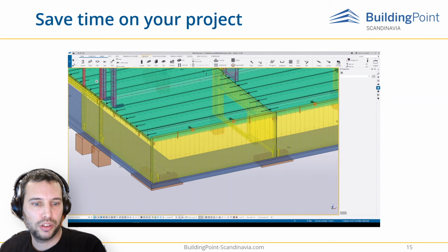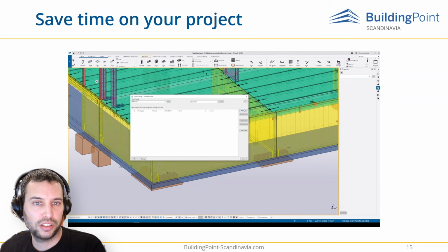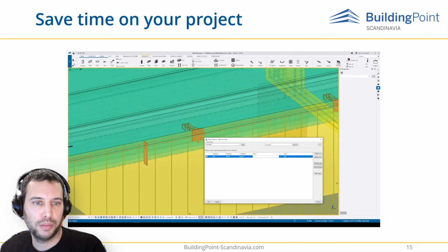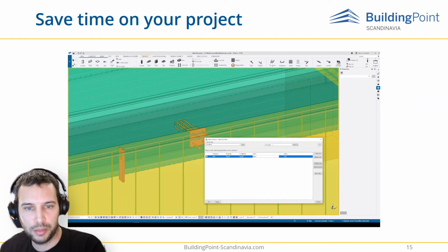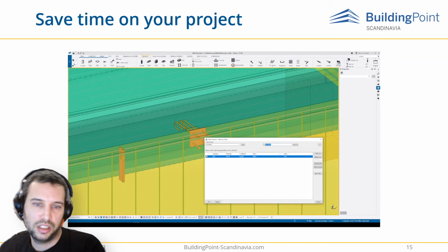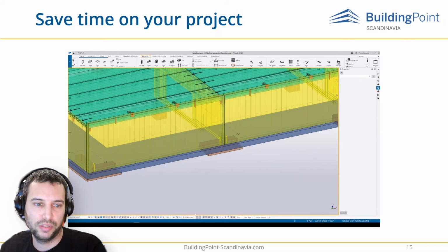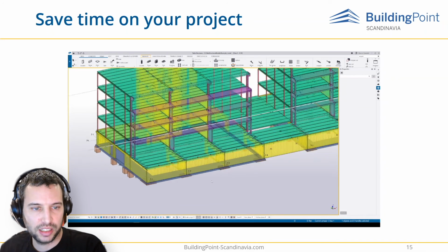So I'm gonna start the creation of the selection filter, add row, select from the model, press my metal plate here, remove some of the unwanted functionalities, sorry, naming, press the star for making it more versatile, and save the setting. Now I have a selection filter. And of course, I need to make sure that it's active to make sense. So now I know it's active and I can select the objects.